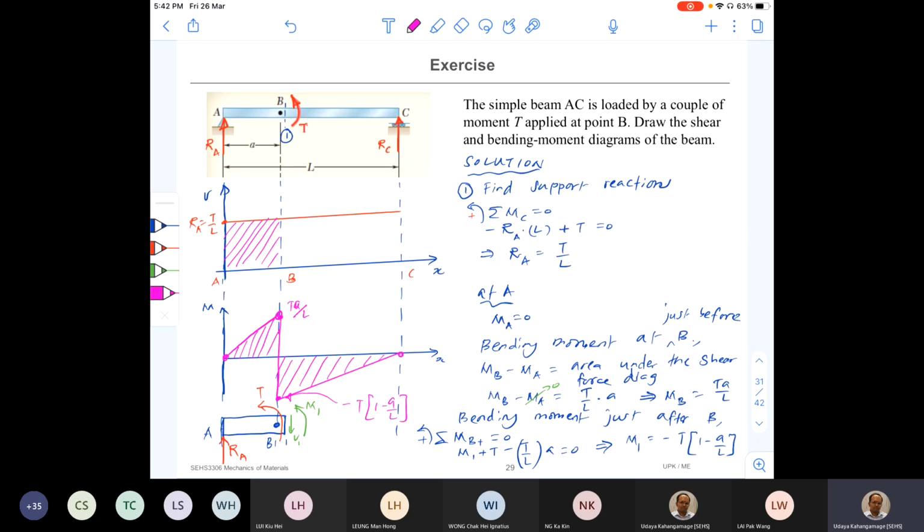So the bending moment curve becomes discontinuous at moments, and the shear force diagram is going to be discontinuous at concentrated loads. Okay, so that's another pattern that we can observe. By making use of these patterns, we can construct shear force and bending moment diagrams faster.